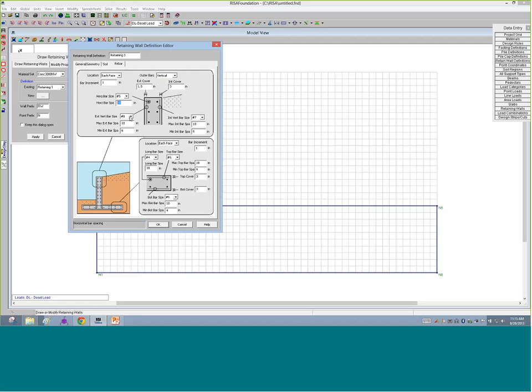Sometimes, whenever I've worked with construction, I like to keep these consistent. So I'm going to change it from the number 8 to number 7. I'll have both the external and the internal bars be number 7, so I don't have any problems in the field worrying about a bar size change. Maybe you need it later, but I always like to match those if you can.